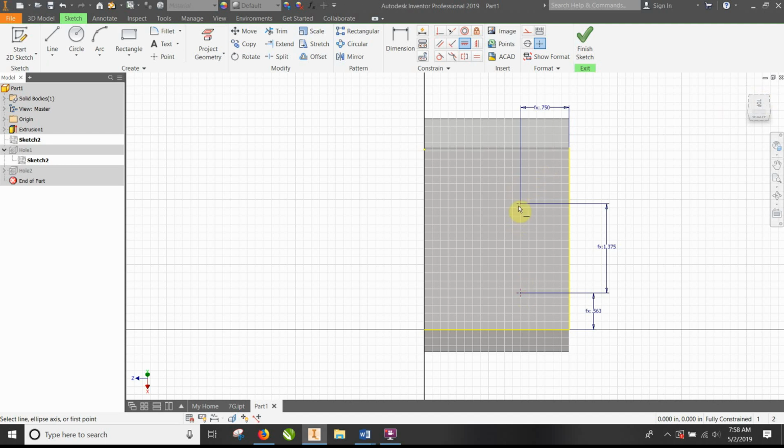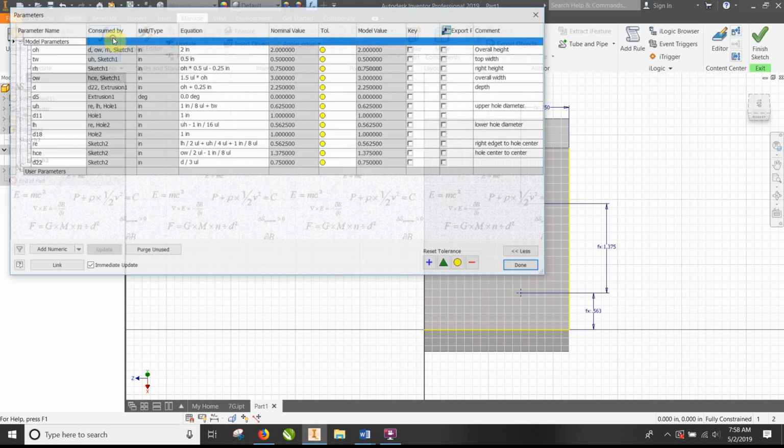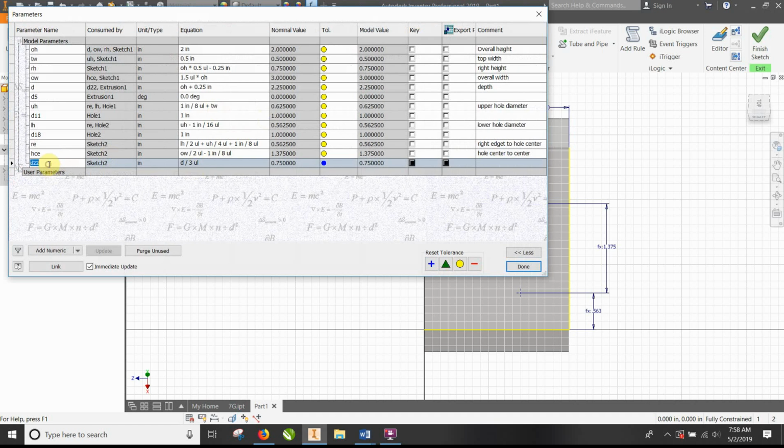So now they're both on the same thing. These are called parametric constraints, but if you want to do a geometric constraint, you can align these both on the same line and make those a geometric constraint. All right, let's go back, we'll change that last one. And this one is called the back edge hole to center, so BE, back edge hole to center. Done.